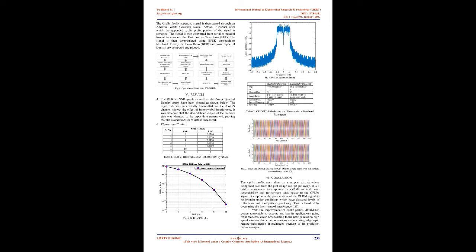Since the OFDM signal is a linear combination, the whole process is to be done only once to the OFDM signal, rather than repeating it with each and every subcarrier. In our paper, cyclic prefix length has been considered to be 7% of the OFDM symbol length.